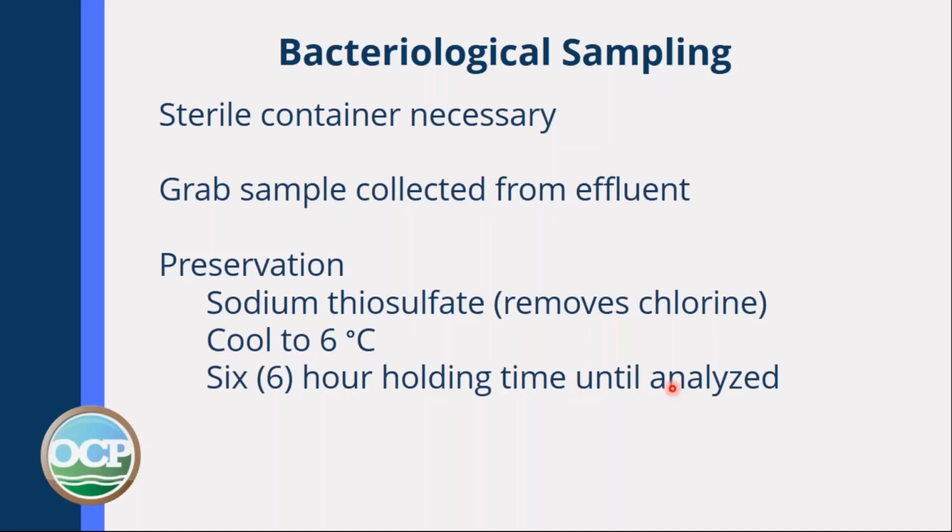Anytime you test for bacteria, you've got to have a sterile container. So don't just sort of pick one off the shelf and open it up and sniff it and say, yeah, that's clean enough. It will be a grab sample from the effluent. Of course, there's no point in testing for coliforms on the effluent because it's going to be full of them.